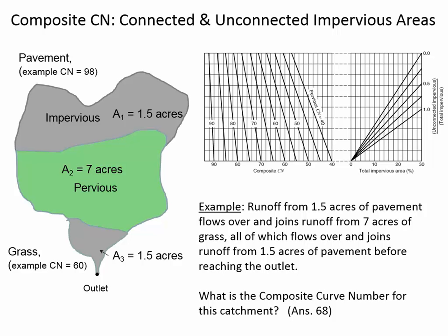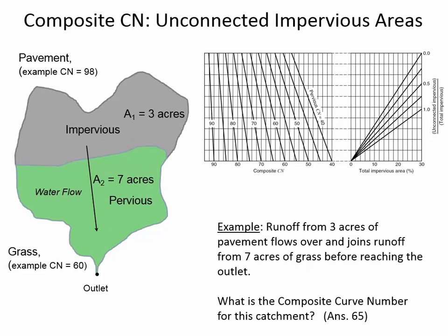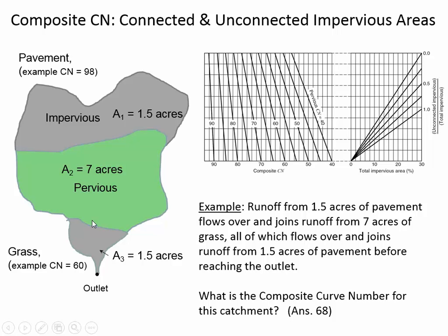So remember that when we were just looking at the previous example just a moment ago, the benefit of this is that some of that extra runoff from the impervious area is going to have a chance to go down into the grass. But here, the part that's in area 3, this impervious part here, all of the runoff from here is going to go straight into the outlet.